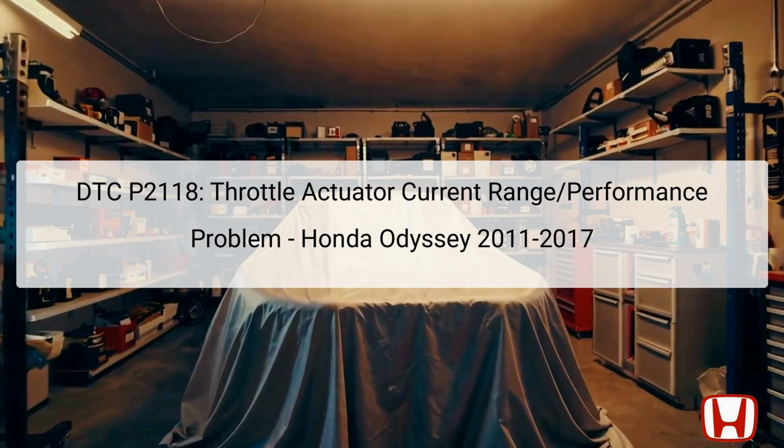In attempting to address this trouble code, technicians should first utilize the HDS, Honda Diagnostic System, to retrieve and clear trouble codes and examine freeze frame data to better diagnose the issue. Subsequent procedures will involve checking connections and continuity to determine the root cause of the malfunction.